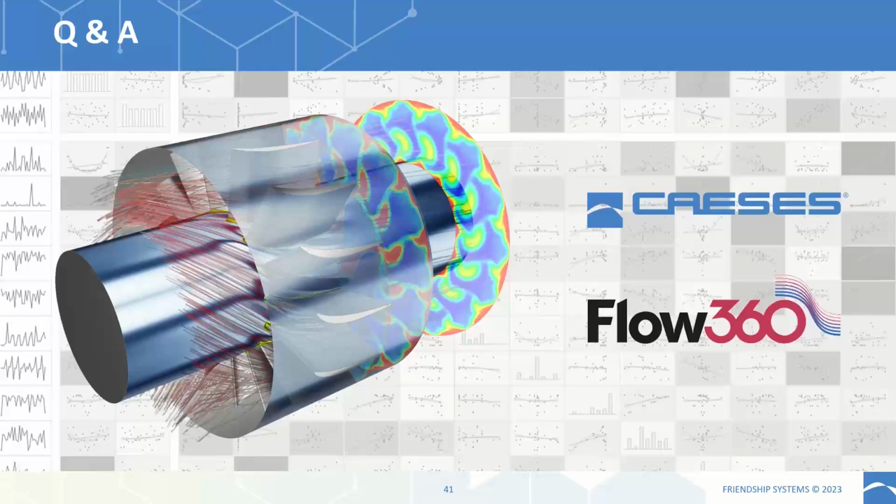Before we get started with the actual questions, I have just two clarifications that I wanted to add for Payam's presentation. First of all, about the optimization, just in case you're wondering, the optimization runs that we performed after the initial design space explorations had a very low number of designs. The reason is that these were so-called surrogate-assisted optimizations. We used the database that we created in the initial design exploration with the Sobol algorithm, as Payam mentioned, and then we fed that database into a surrogate model.